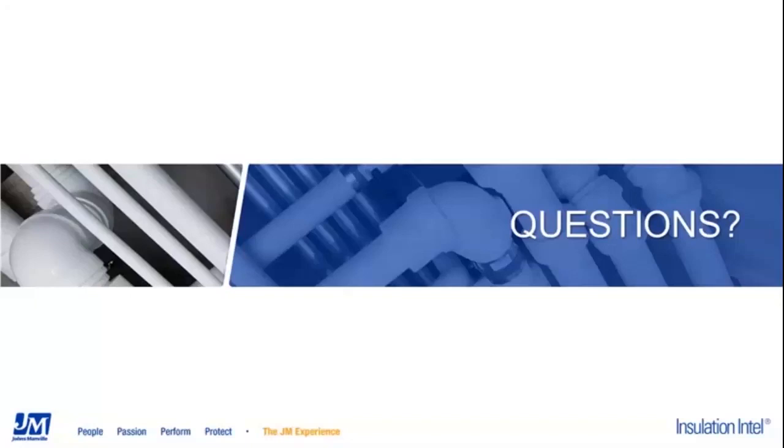I have not done that comparison. I can tell you that according to ASTM C871, the leachable chloride for the Trymer 2000 XP is 58 parts per million when it's tested in accordance to that ASTM standard. John, can you tell us what the other one is?